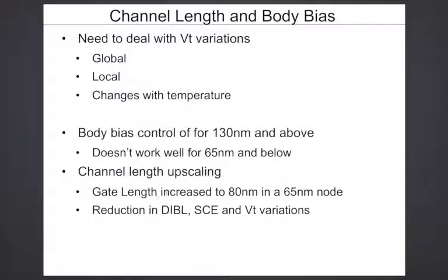One interesting approach to control the threshold voltage is to use the channel length, and instead of using the minimum channel length, you can use longer channel lengths. And what that does, we'll see in the next slide from some work done by these researchers, who have studied the impact of the channel length and how that helps to reduce the variations as well as the leakage.